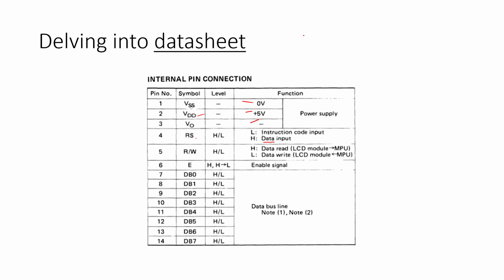For example, if I am sending an instruction to the LCD, 0x36, and I want the LCD to understand that 0x36 is an instruction, I'll pull the register select line low. When register select is pulled low, the LCD will understand that the data it is getting is a command, and it has a lookup table of different tasks to do based on the command we are giving.